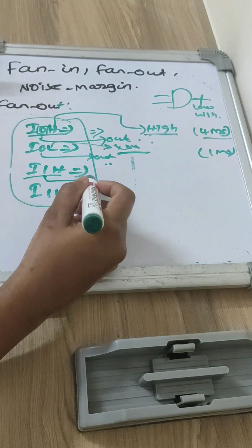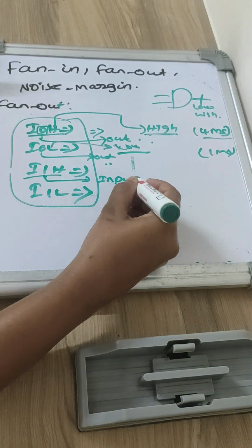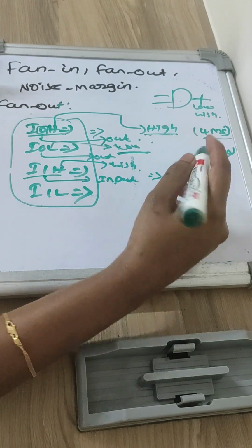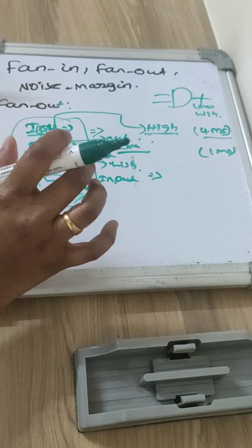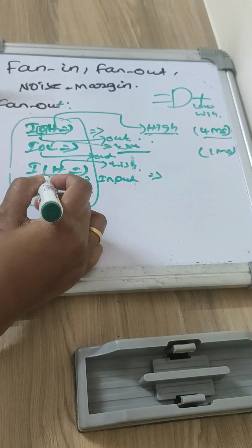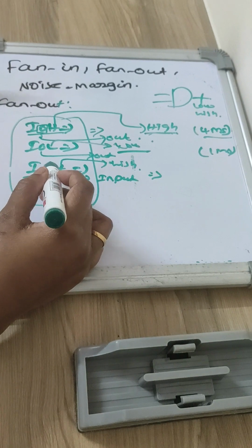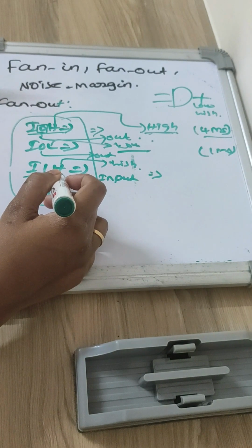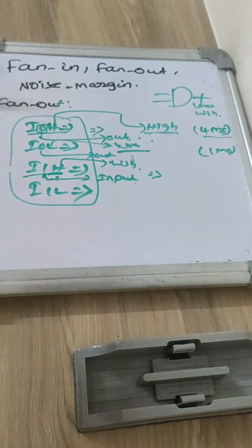So this is, as I am telling, mentioned as input, and this is high. What this is telling is the expectation here: this is the amount of current the input terminal is expecting when you are trying to drive a high value at the input from the external side.